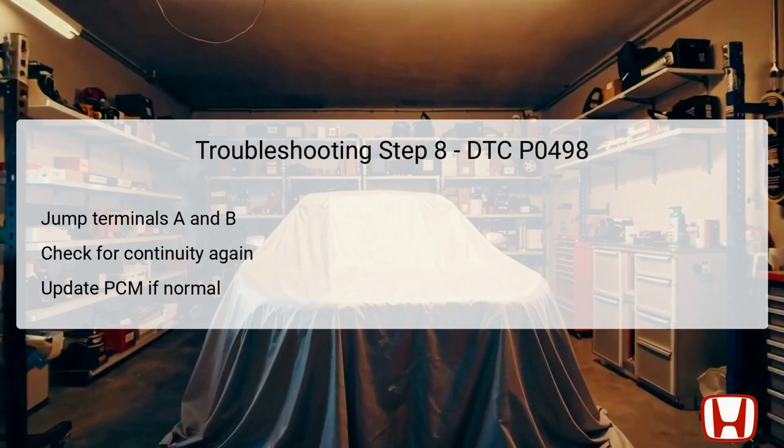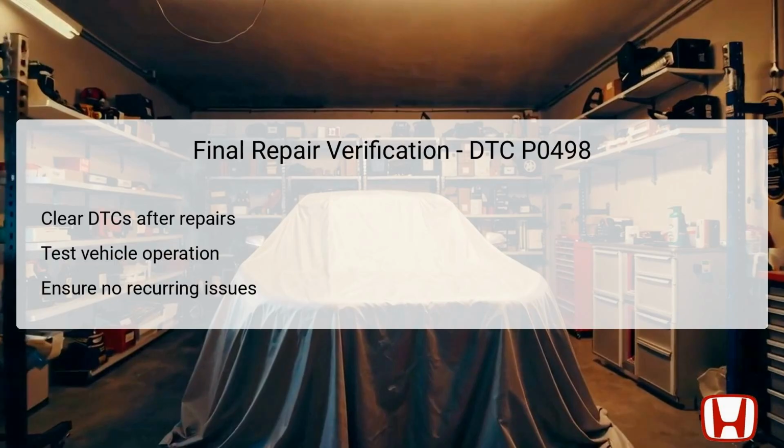If continuity is confirmed, it indicates that the wiring is intact, and all that may be left is to update the PCM, or Powertrain Control Module, with the latest software. However, if continuity does not exist, repairs must be made to the VSV wire leading to the EVAP canister vent shut valve. After completing all necessary repairs based on the diagnostic steps, proceed to clear any DTCs stored in the system using the HDS. Once the codes are cleared, test the vehicle to verify that it operates smoothly without triggering